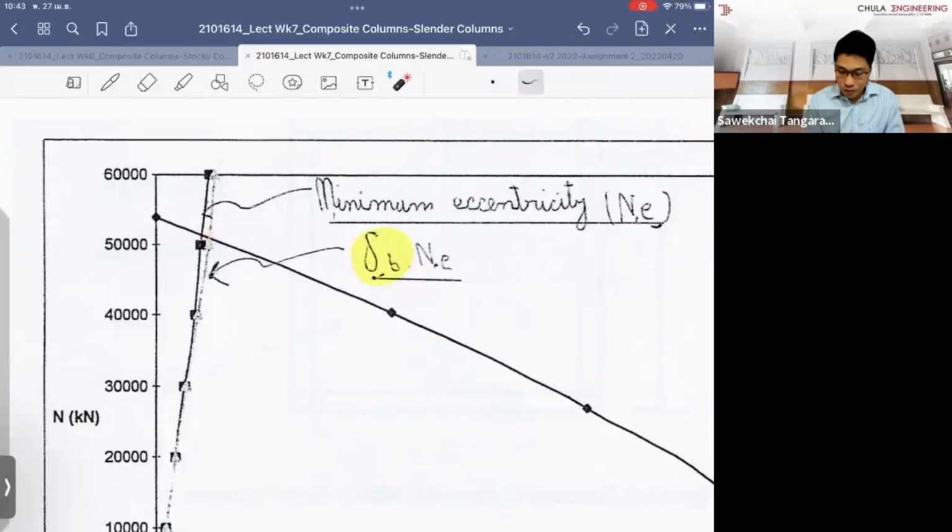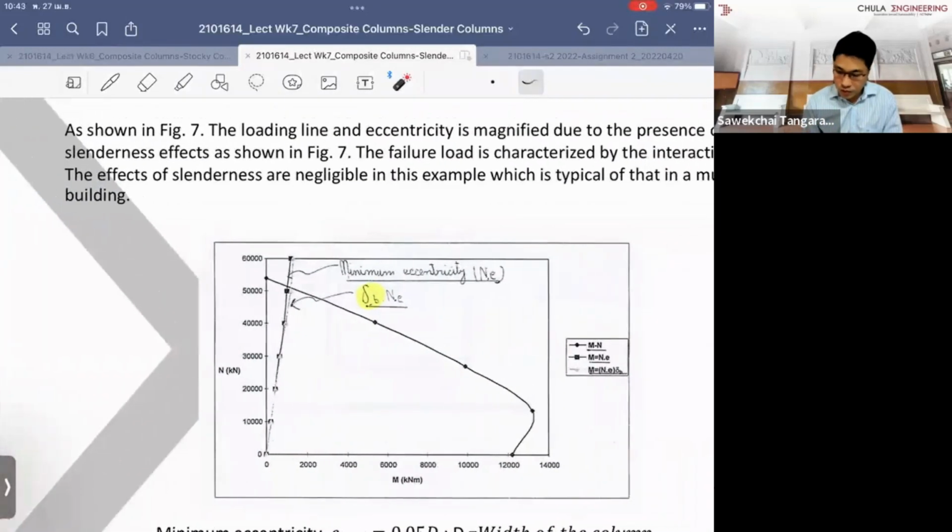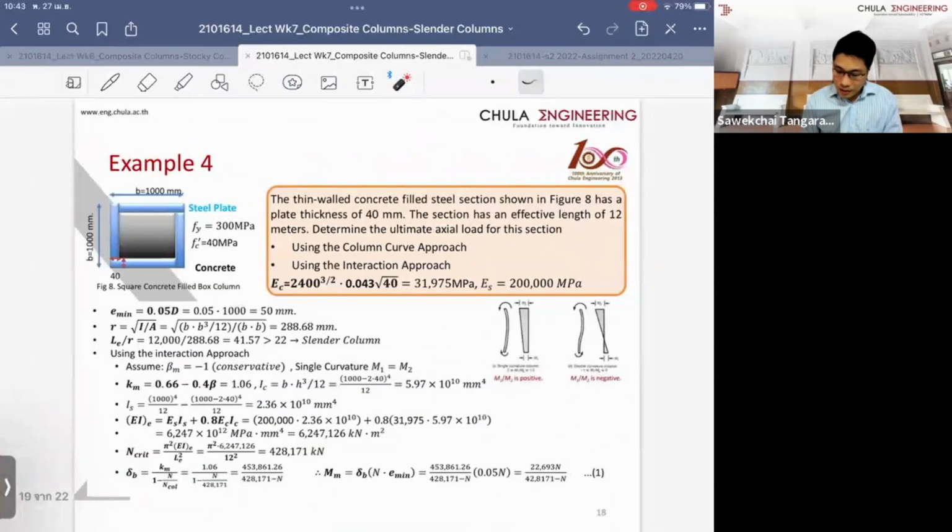So you have to basically use Excel, or if it is a linear equation, you use two linear equations and you find the intersection point between them. And then, you have the nonlinear equations here and the linear equations here, and you substitute the equations so you can get the intersection point between them. And you can tell which one will give you the failure. If the question doesn't tell you the load and they ask for the maximum load they can apply, you have to do it this way.